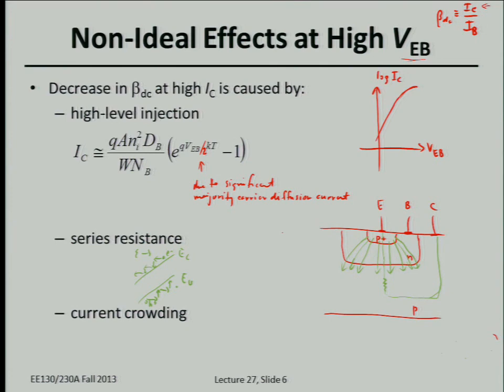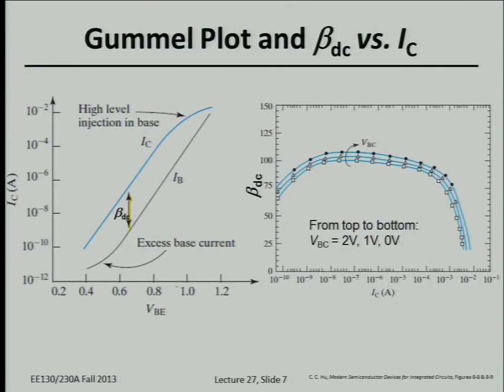So that's qualitatively what that is all about. So bottom line is, if you plot on a log scale both the collector current, IC, and IB, sorry, each of these should be a straight line, okay? And what is the slope of that line? How many millivolts per decade? 60 millivolts per decade, yes. So both IB and IC should be 60 millivolts per decade.